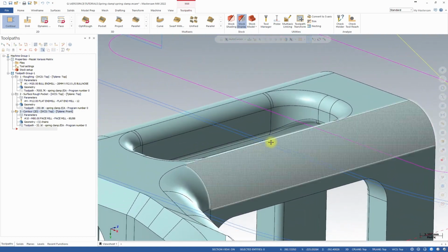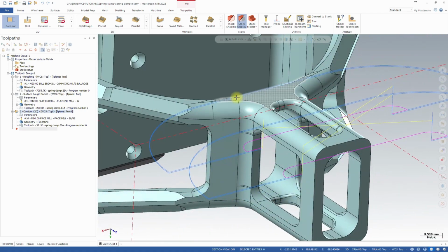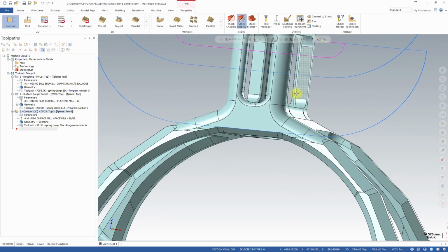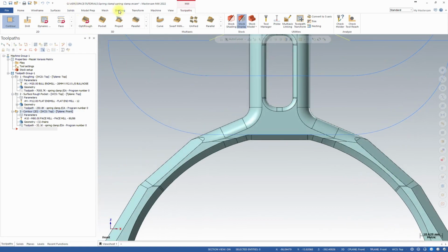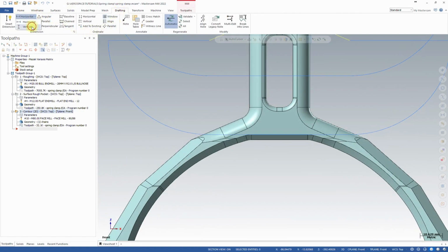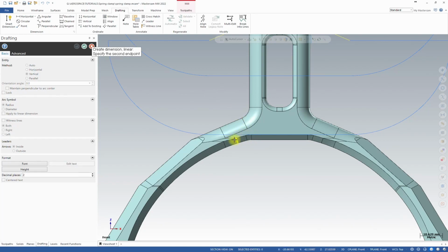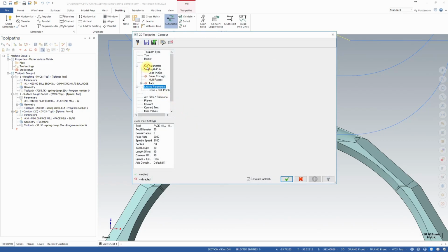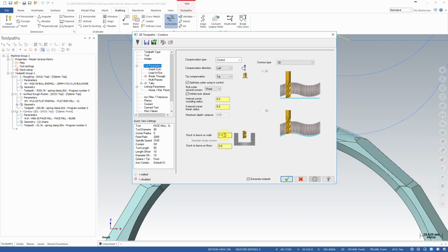So we should have 2 cuts here and 2 cuts here, which is okay, but we still have something missed here. Okay, so let's switch to front tool plane and construction plane, and I'm going to measure that distance between this edge and this edge, and it is 1.82 millimeters. Okay, escape, 1.82. So what I'm going to do is, in the cut parameters, I'm going to shift my tool minus 1.8 against the edge, or even 7.5.